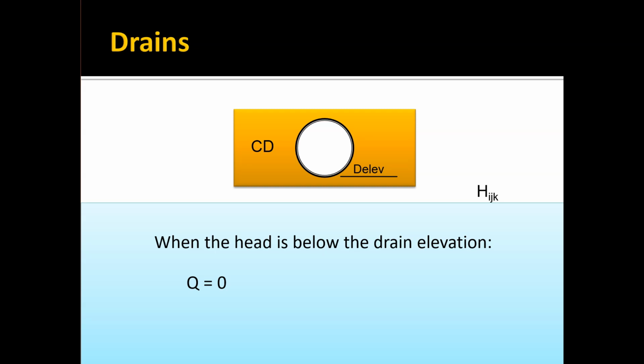And so sometimes we use drains just to represent an area in our model where if the water table gets high enough, it's just going to discharge. Now, you would think, why doesn't that always automatically happen? If the water table gets above, let's say, the top elevation of your MODFLOW grid, no, that's not the case. It only happens if you mark that as a drain cell and give it, say, a really high value of conductance. So drains are very useful and very commonly used.